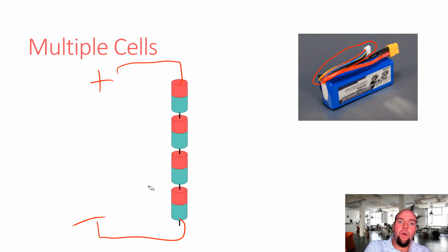Well, one way you could charge this battery is to just apply a big giant voltage here. So let's apply 3.7 times 4, that's 14.8, maybe. Well, let's do 4.2. 4.2 times 4 is 8.4, 16.8. So you're applying 16.8 volts here, but then you're measuring these voltages here.